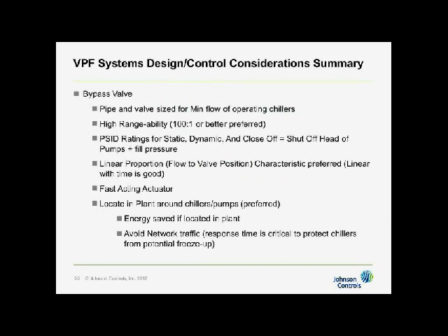Bypass valve, we talked about these things up here. We also want to have a high rangeability for the valve, 100 to 1. Rangeability of a valve is the max flow that the valve can handle, ratioed against the minimum controllable flow that the valve can handle. We need to have PSID ratings for static, dynamic, and close-off equal to shut-off head of the pumps, technically, plus the fill pressure.